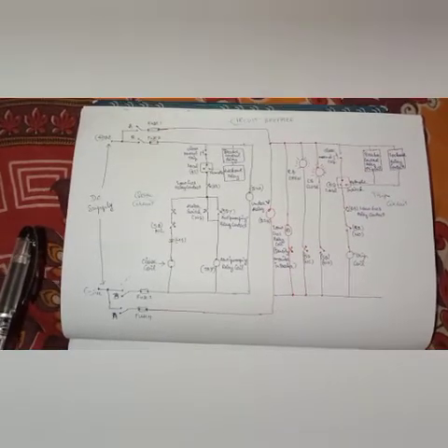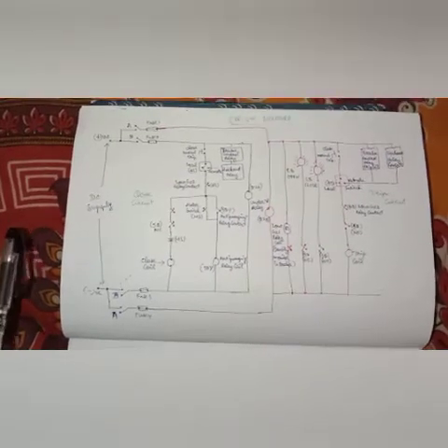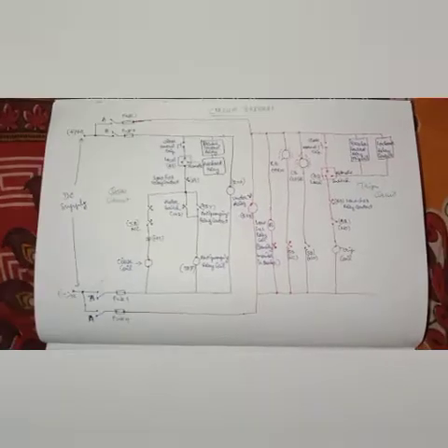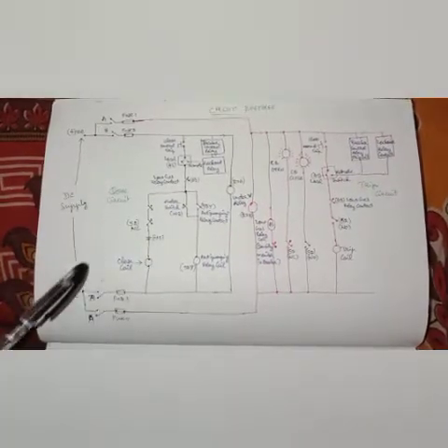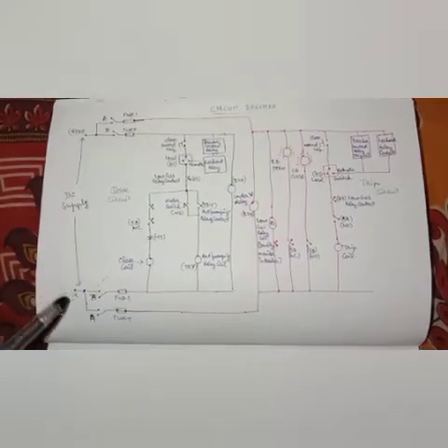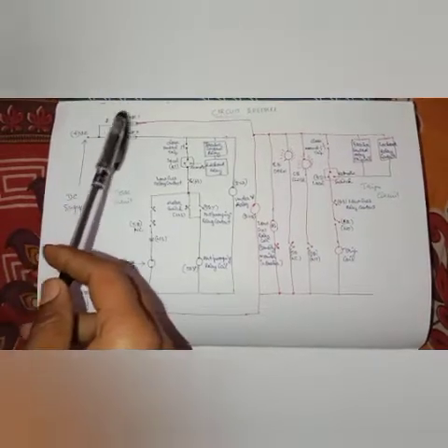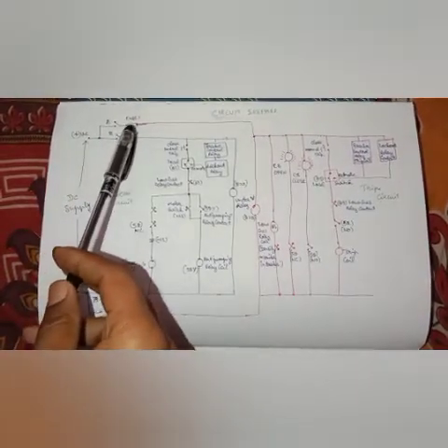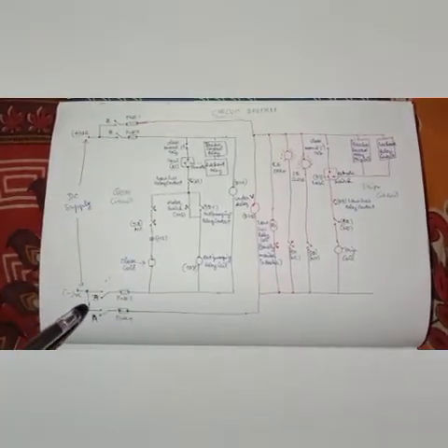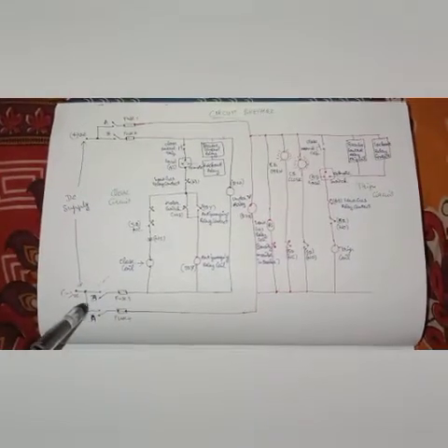In most substations we use DC as the control supply, and here we use two MCBs, A and B, each with a positive supply and a negative supply. Each MCB is connected further to fuses: MCB A positive and negative side, MCB B positive and negative side.